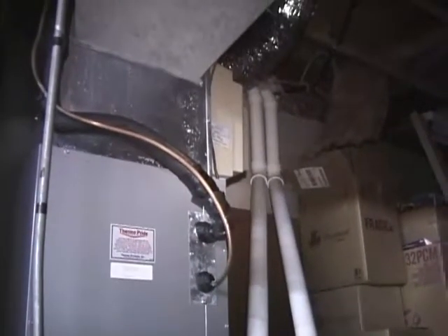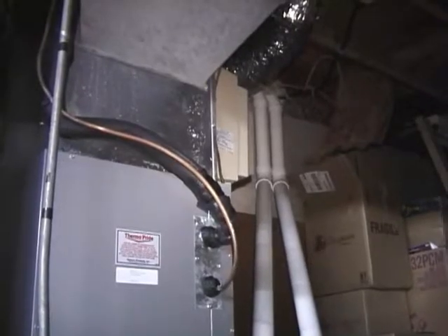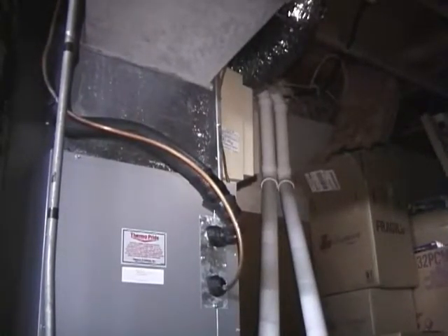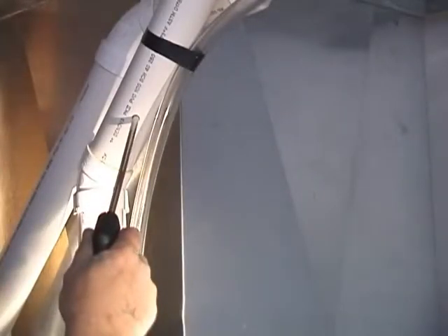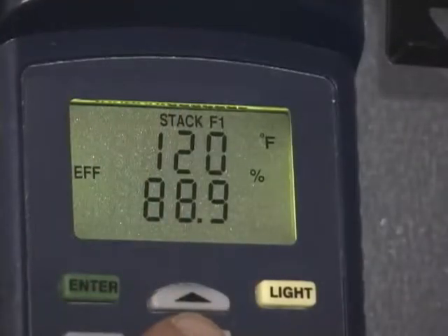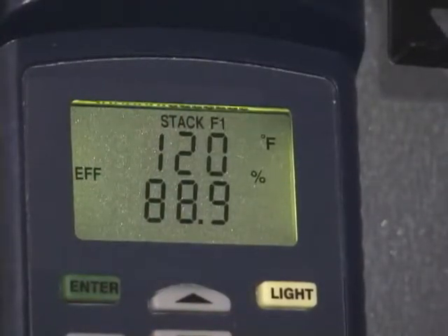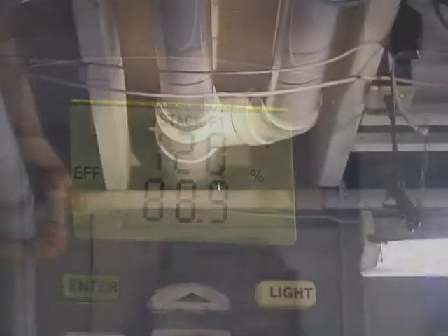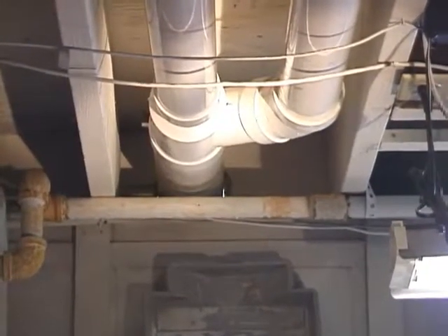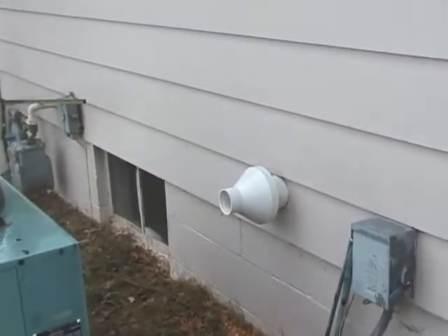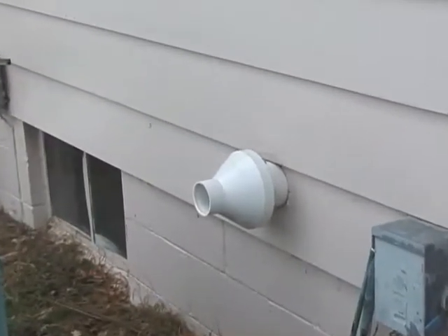Category 4 appliances are usually high-efficiency condensing models. The combustion gases have been cooled by the appliance's secondary heat exchanger to a point where additional condensation is likely to occur in the vent. And most are sealed combustion two-pipe units, in that they draw all combustion air through a pipe from the outside of the building, although not all are.